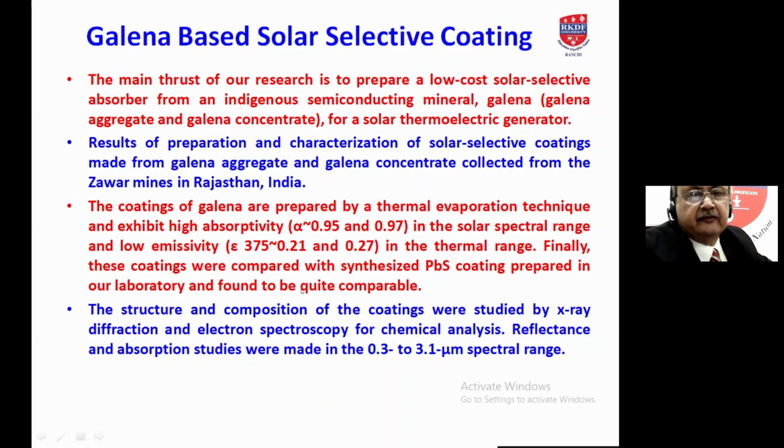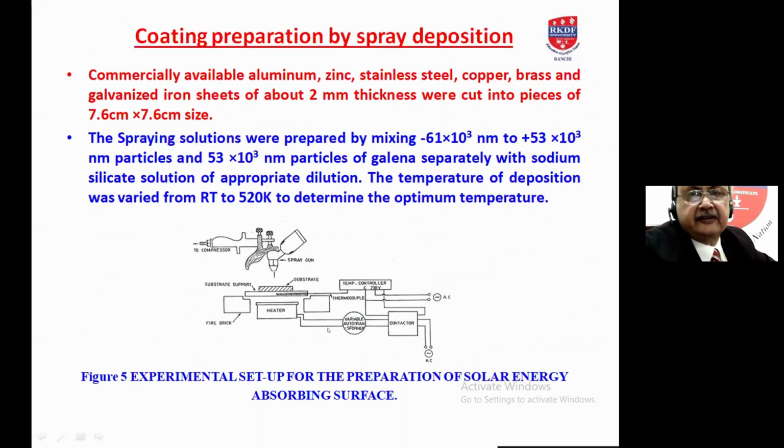Finally, these coatings were compared with the synthesized PbS coating prepared by our laboratory and found to be quite comparable. The structure and the composition of the coating were studied by X-ray diffraction and electron spectroscopy for chemical analysis. Reflectance and absorbance studies were also made in the 0.3 to 2.1 micrometer spectral range.